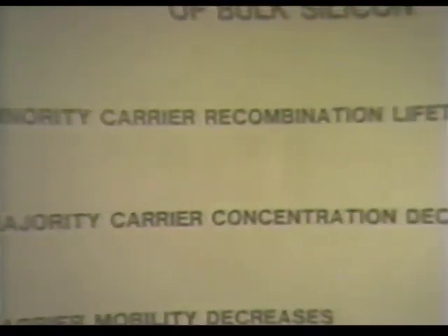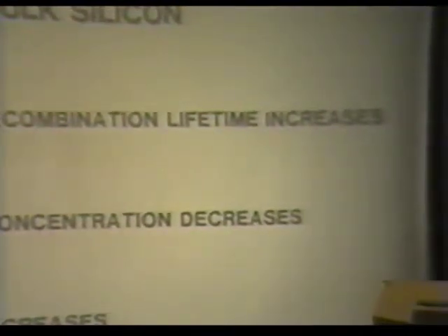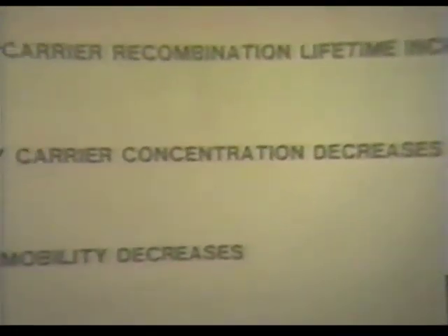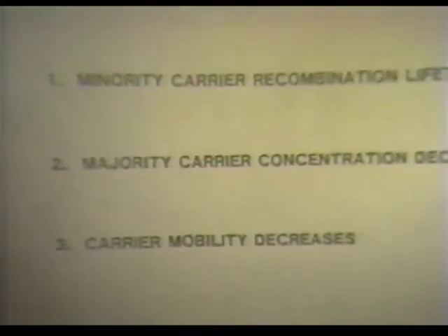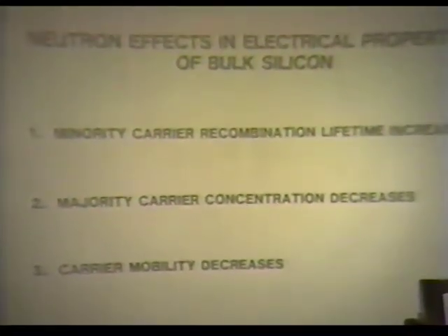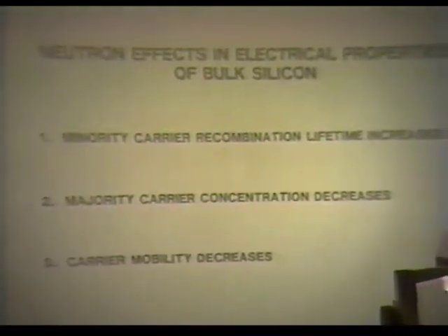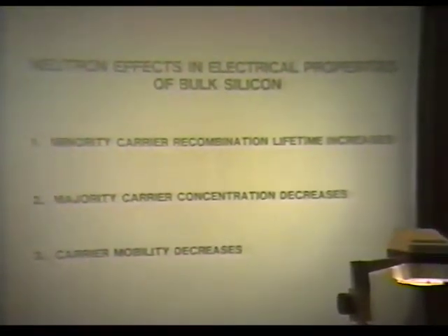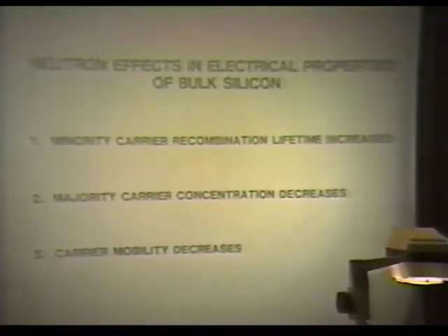And what do they do? They change the gain of your transistor. And how do they do that? Because if you remember your transistor profile, when your electrons, in the case of an NPN for instance, are injected from the emitter into the base region and you try to collect them over at the collector, you've created defects in the base region. Now I'm going to talk about the base because that's one of your primary interest areas. That's one of your critical volumes, because that's where the minority carriers are trying to move through.